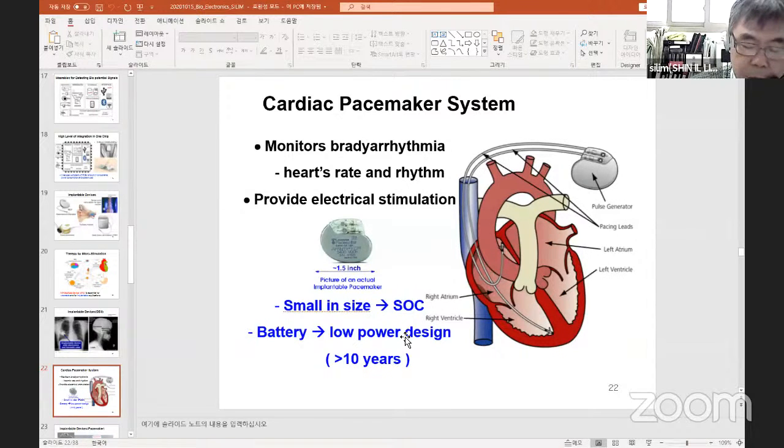Several factors contribute to the success of the pacemaker, among which are size and battery longevity. The pacemaker system, as shown in this slide, consists of two components, the pacing lead and the pacemaker device. The pacing lead connects between the heart and the pacemaker device. It is a flexible, insulated wire with an electrode tip. This tip, inserted through the vein in the heart, carries impulses from the pacemaker device to the heart, stimulating the heart to beat.